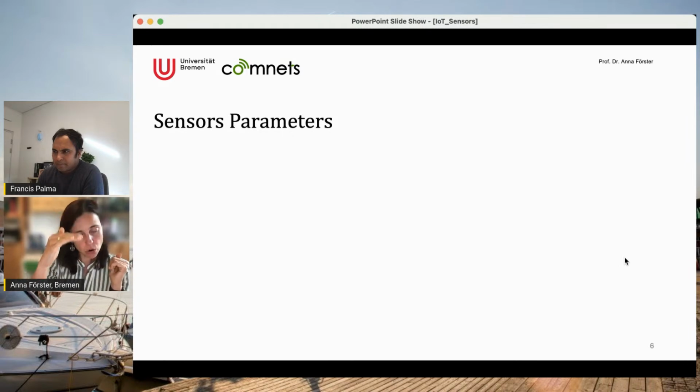I have some sort of a program which looks like a loop, right? And whenever something interesting is happening, I can interrupt the main program and say, hey, something came on the sensor, hey, you have a new tick from the real-time clock. These events are called interrupts. This is quite important to understand, because the microcontroller really has a single process only.